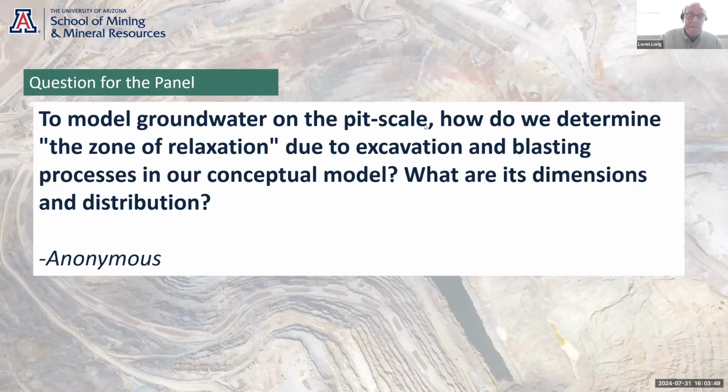And it's not the same for all rock masses either. This rule of a quarter to a third of the height depends very much on the characteristics of the rock, how brittle or how ductile it is, how strong it is.